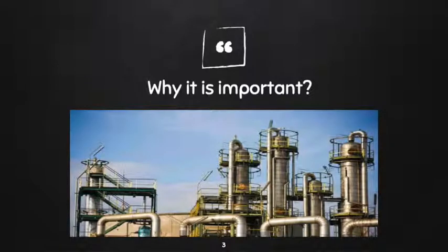Alkylation is a secondary refinery unit operation that many refineries have because it adds high-octane hydrocarbons to motor and aviation gasoline. High-octane hydrocarbons are needed to help prevent auto-ignition of gasoline, also known as knocking, in an engine and to meet recommended engine octane ratings.